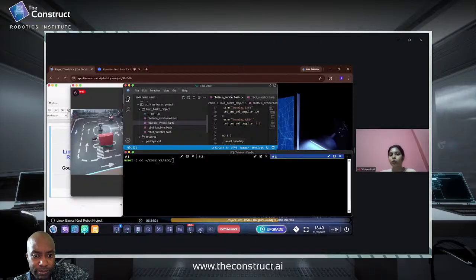This helps to control the speed of the rotation. The higher value results in faster turning, and the sleep duration controls how long the robot keeps waiting while turning, which directly affects the angle of rotation.